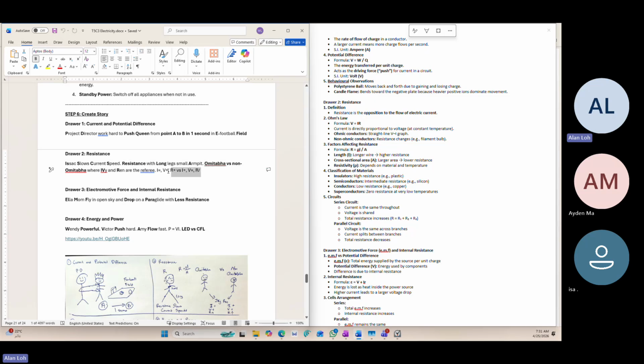Then I have this formula. Right? This formula is to reflect that this is the series, this is the parallel. Remember when I say parallel, there's a big difference from series in terms of resistance. The resistance is lesser. So see, resistance is divided for parallel. Then resistance for series is added up, so it's getting more and more. Then for the voltage for series, it's getting more and more. But for the voltage for parallel, it's consistent.